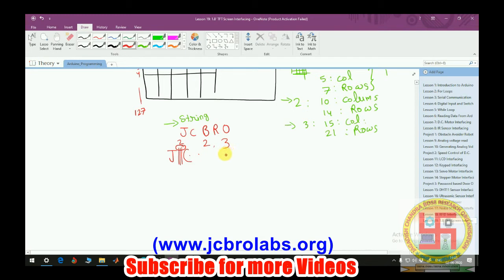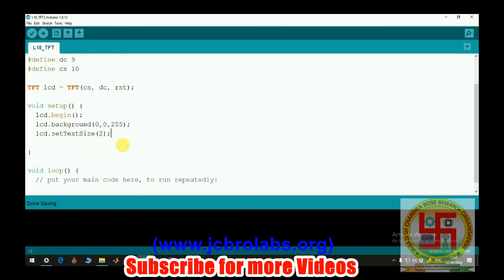Based on this information, we can easily find how many characters we can display in a single row, and how many rows we can put on the entire screen. That is very important. Right now we are setting the size to 2, so it takes 10 by 14 pixels to display a single character.